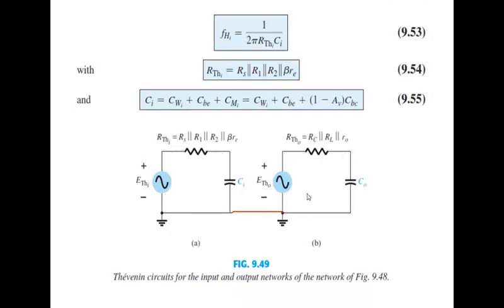So you end up with this simplified circuit in which you can see both have the same topology: a resistor and a capacitor, a resistor and a capacitor. So each individual section forms a simple first order filter, and this filter would be a low pass filter.